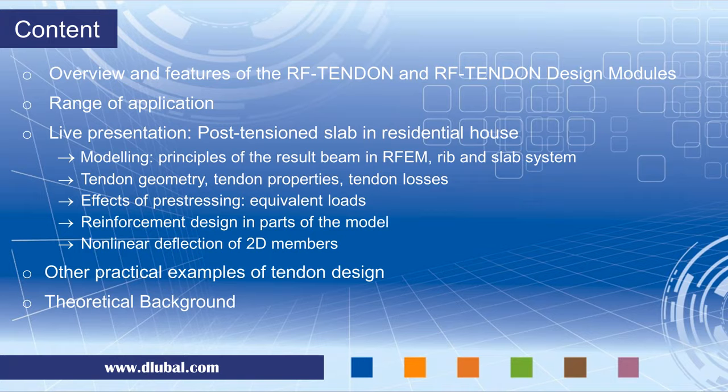We will start with the modeling in RFEM. I will explain the principles of so-called result beams and the system rib and slab. And then I will switch into the external module to show the tendon geometry, properties, losses, the effects of pre-stressing, and also some reinforcement design.